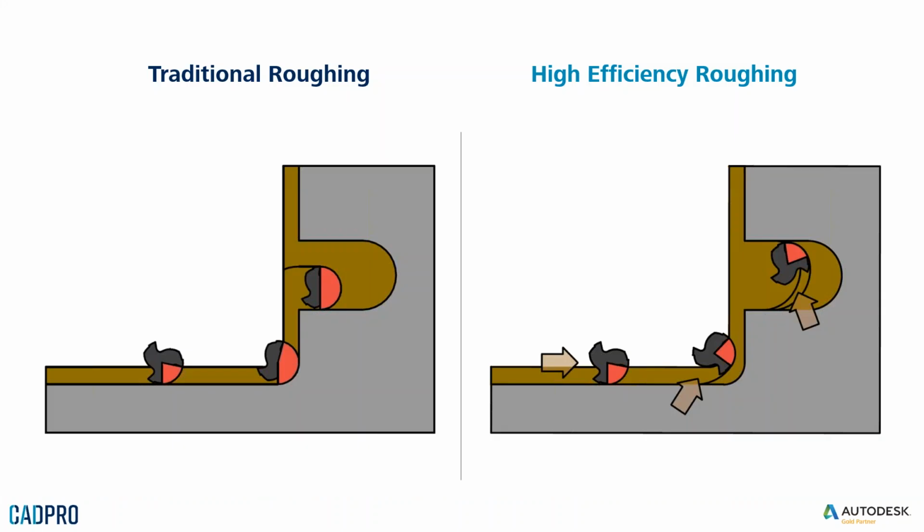So what is it? On the left-hand side here, we've got traditional roughing, like 3D pocket or 2D pocket as the equivalent toolpaths in HSM. As the tool moves, you can see the red pie section of the tool in the graphic. It's coming along the bottom wall there, a nice, easy cut, maybe about 45% radial engagement. As soon as it gets into the corner, it over-engages, and then as it goes into a full slotting scenario, it's 100% engagement.